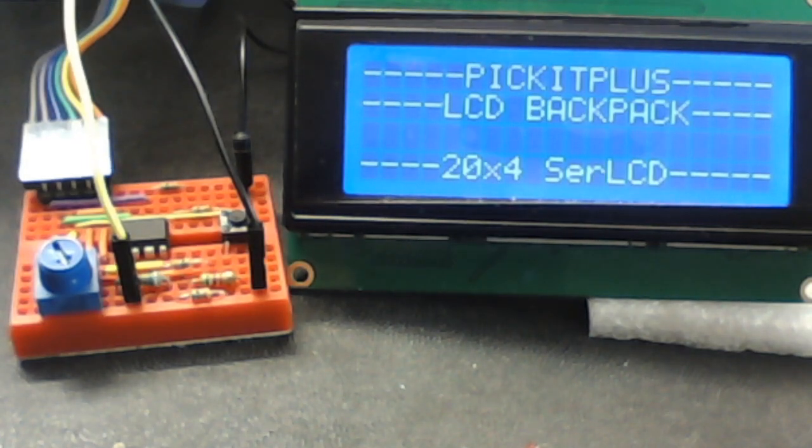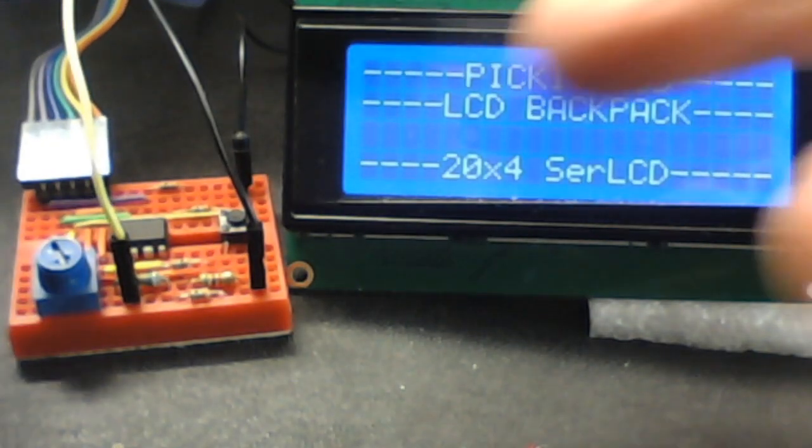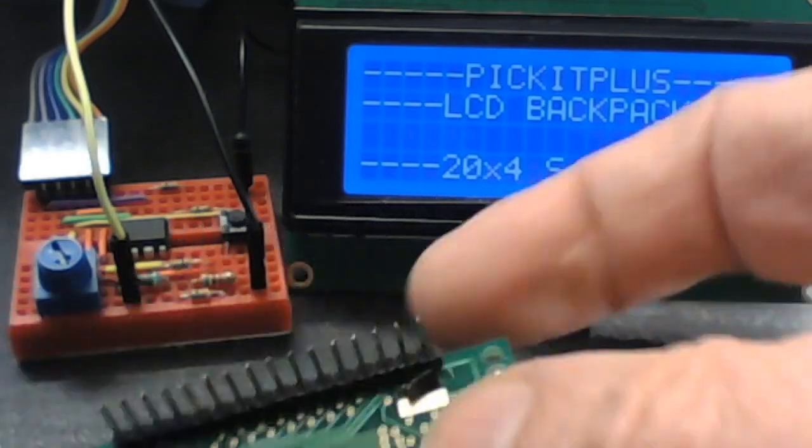Here we go. I've grabbed a series of LCDs and I'm going to show you them and why I'm using serial today to justify it. This is an LCD. They're all LCDs of some sort, and these all have different connectivity options. And Great Cow Basic can control them all. This one has an 8-pin connector. If I go into the lab, I think we might see it a bit better. This one has a whole series of pins. Well, I clearly can't connect the 8 or 4 data pins that were required to that little chip.